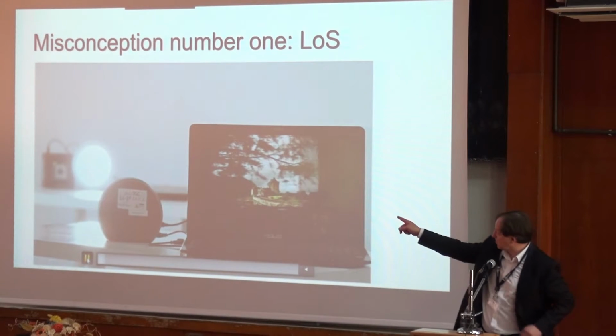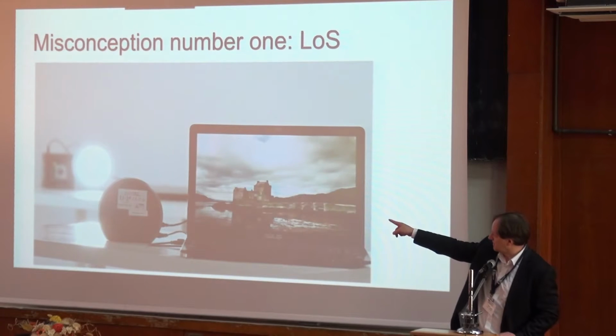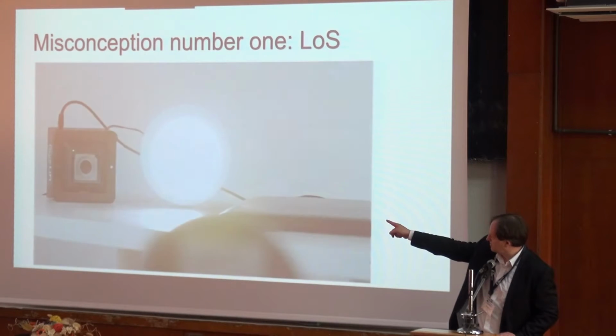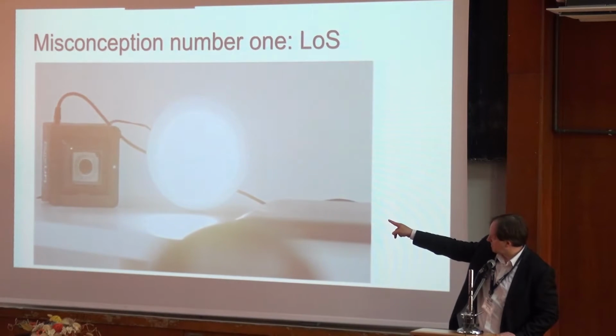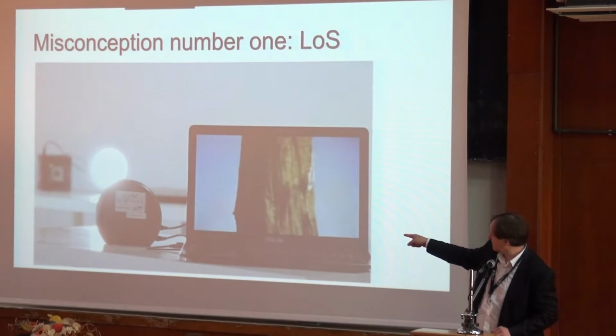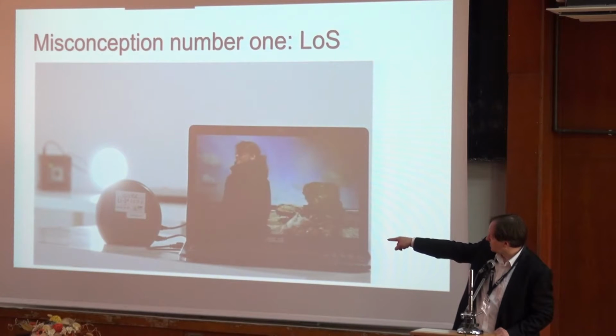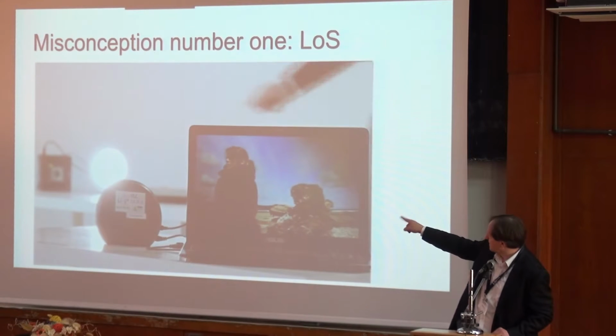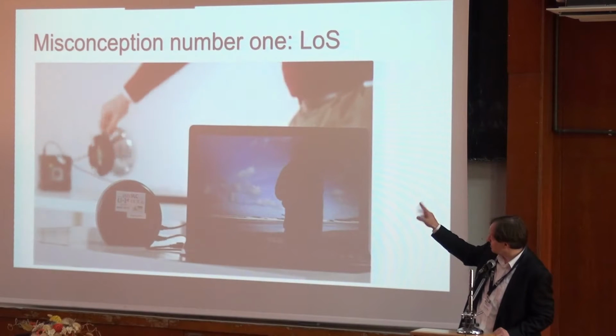We have a LiFi enabled off-the-shelf LED light, a downlighter there. We have an access point connected to the light. The red circle is the infrared filter for the uplink. The thing in the front, about 3 meters away, is the receiver dongle connected to the USB, and we transmit a video. Now we turn the light around.